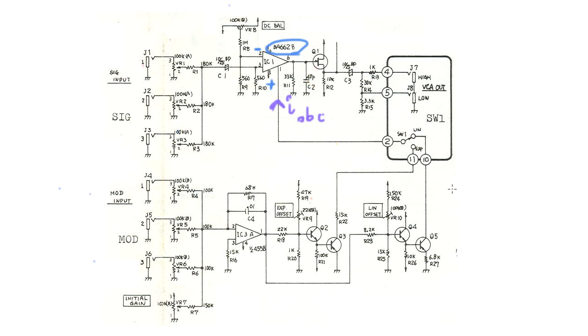As you get to very high frequencies, this will start to look like a short circuit, and the output here is getting shorted to ground. So whatever current is coming out of here doesn't really matter because the output is effectively shorted to ground and you don't get anything out. So before we do any kind of algebra or anything, we know that this capacitor will have a low-pass filtering kind of effect.